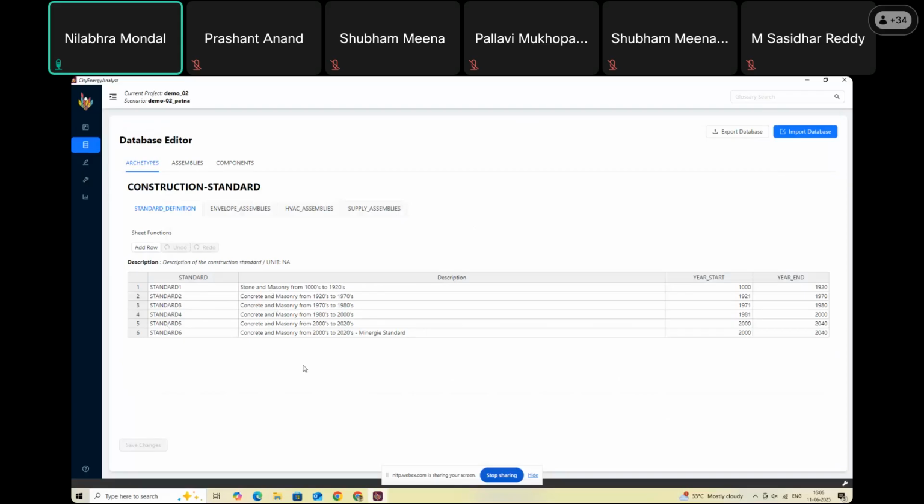But all those Excel files, City Energy Analyst accesses through certain external directories, and those directories are made by default by them. If you want, you can change those directories following a certain file type. Say it is in .txt format, so you can do the edit in .txt format and resave it. You can open those files here. There will be no issues.